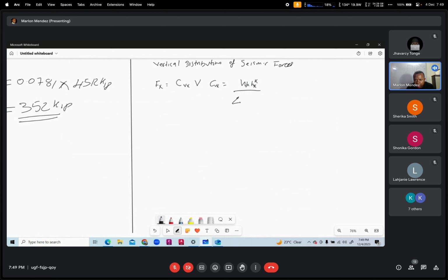So it is a summation, right? Moving from one floor right up to the end of the floors, as we sum each the weight times the height. Okay. K here is equal to 1.10, based on the period. So what we're going to be doing now is, this is better presented in a table format, and this is us actually distributing the load over the structure.